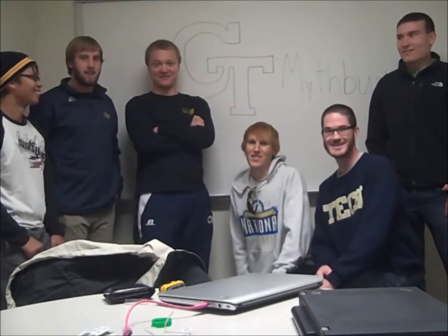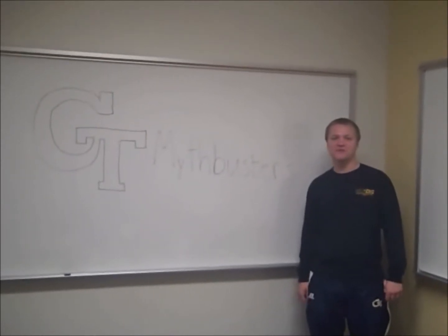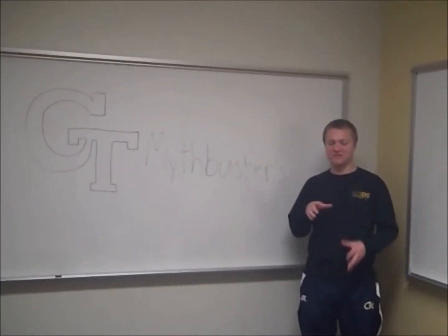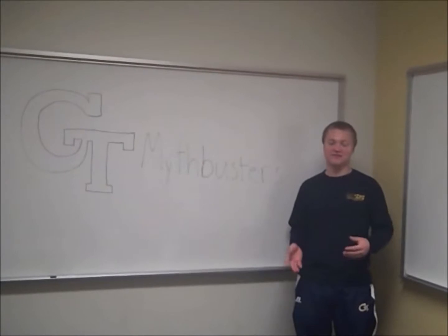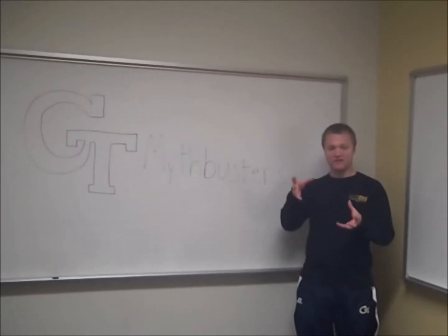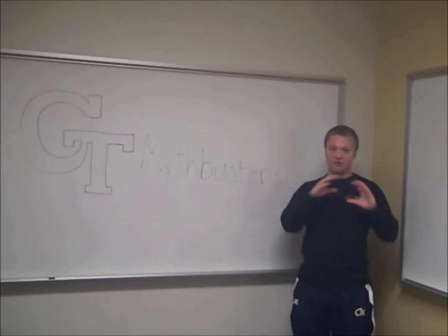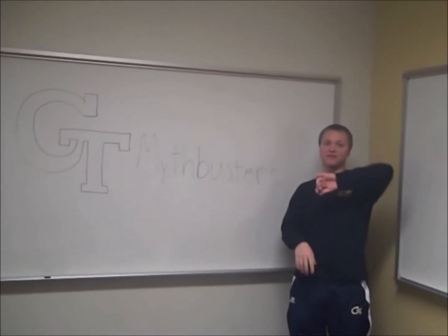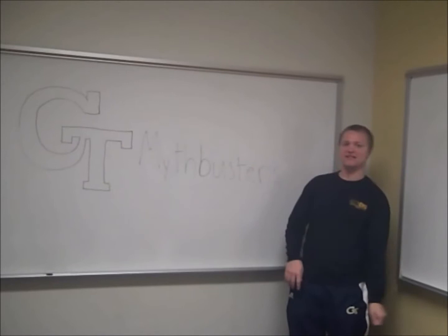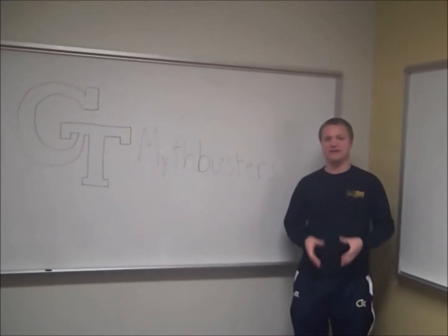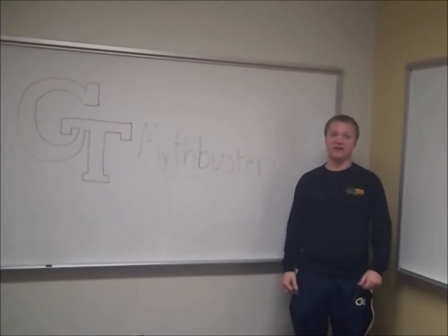The GT Mythbusters. And today we're talking about siphons. So siphons work through potential energy. All states of matter want to be at the lowest energy state. So if you have a container of fluid with a tube, and the tube is filled with the fluid with no spaces of gas, the fluid will go up through the tube, then back down to get to a lower energy state. Now we're going to talk about Bernoulli's equation and the math behind it.